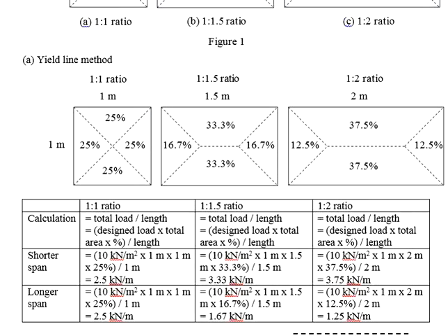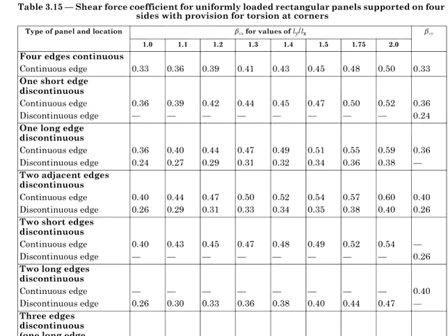No matter the edge is continuous or discontinuous, the same set of U-lines shall be constructed. It makes no difference in terms of the distribution of the load. Whereas the British Standard takes into account the redistribution of the stress as a result of the continuous edge. The continuous edge and the discontinuous edge will have different levels of rigidity that can slightly affect the amount of loads taken by the edges.